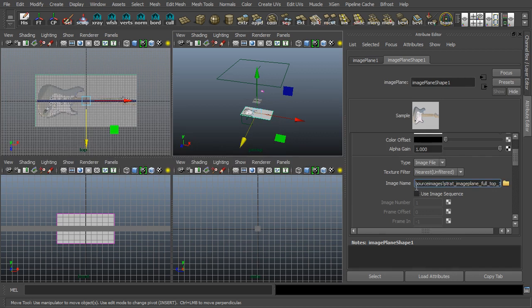So notice there's nothing in front of that now. So this is a relative path. So now every time I set my project, it's just going to look in source images for whatever I open up. So you want to make sure that that doesn't have all that information on the front end of that. And this is a very good sign that my project was not set when I brought this in.